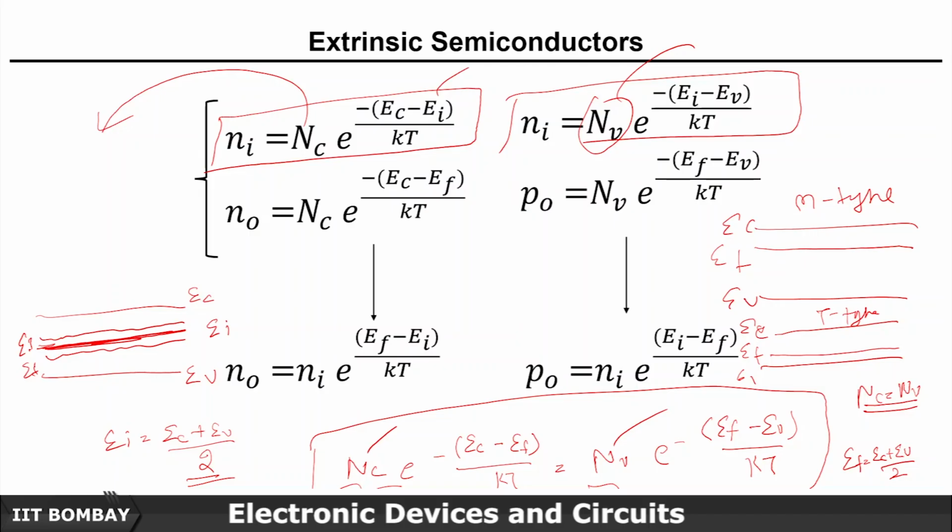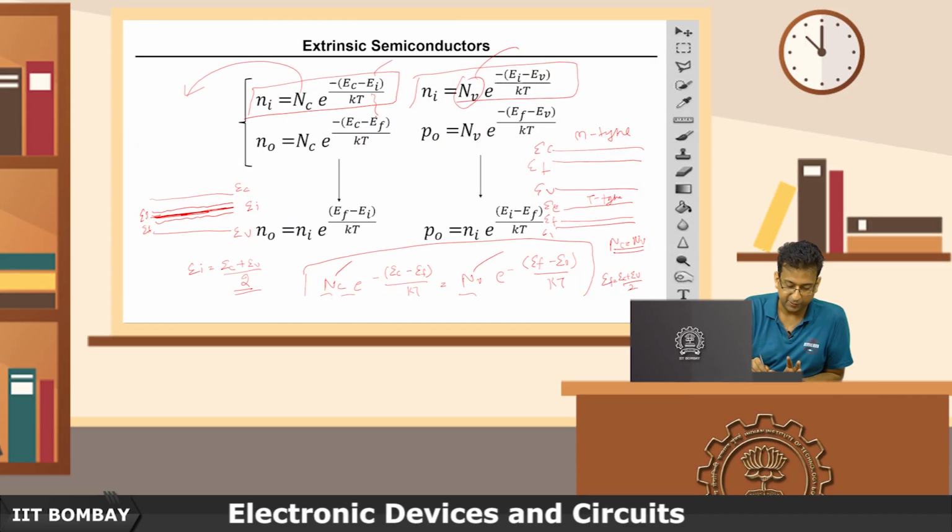As the Fermi energy level gives you the probability, right? We discussed that in detail in the last lecture. It is obvious that it will shift up in case of an n-type semiconductor, and it will shift down for a p-type semiconductor. Irrespective of that, wherever the Fermi energy level moves, Ei is being replaced with Ef in these relations which we derived in the last lecture.